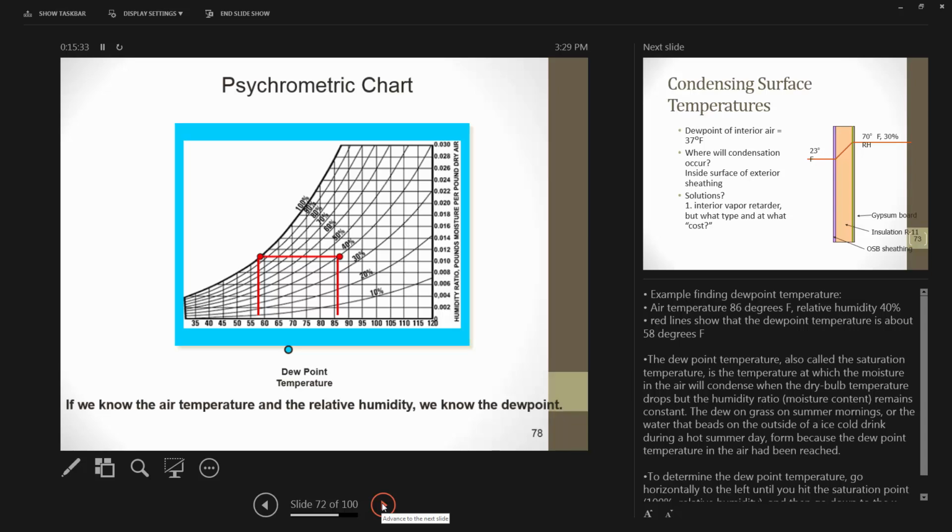Yeah. But again, all that's going to tell you is, at that point in time, based on what the relative humidity is right then and there, and the delta T is right then and there, do you have the potential to reach the dew point inside your wall cavity? You certainly don't want wall assemblies that have a high potential of that, but just having the potential doesn't necessarily mean you have a bad wall assembly. That goes back to what I was saying about the dryability.